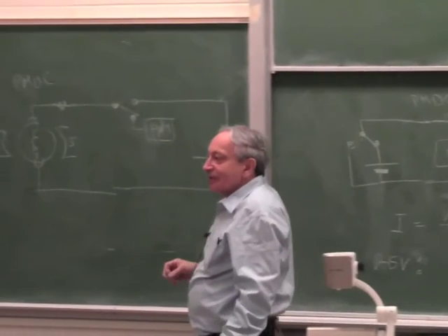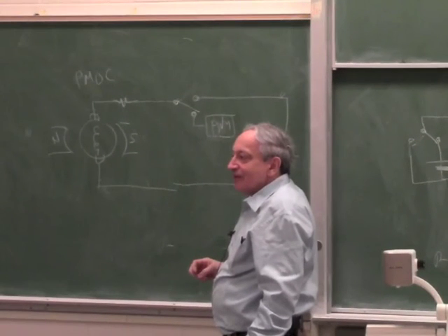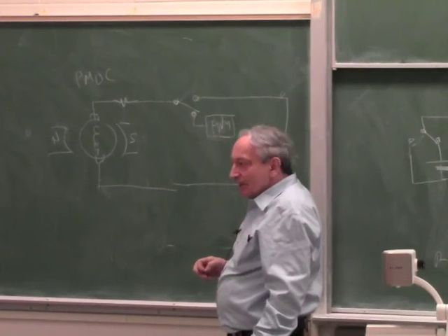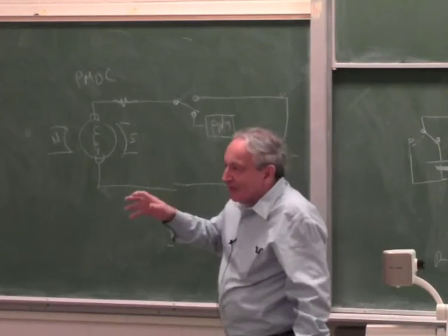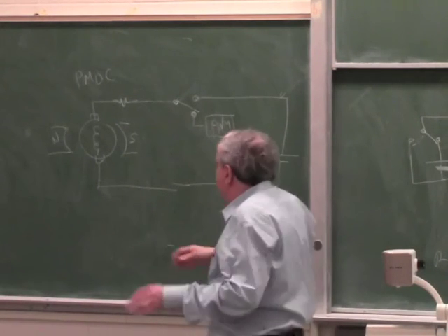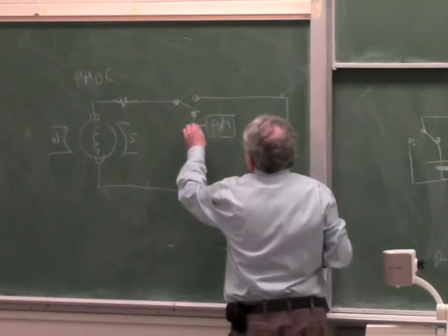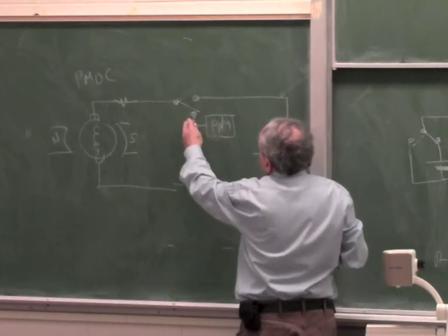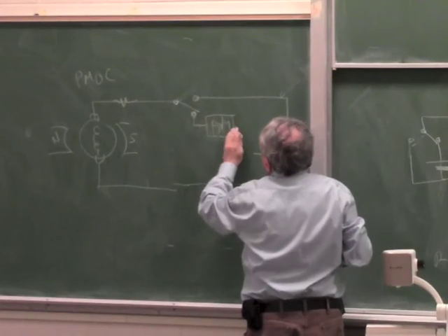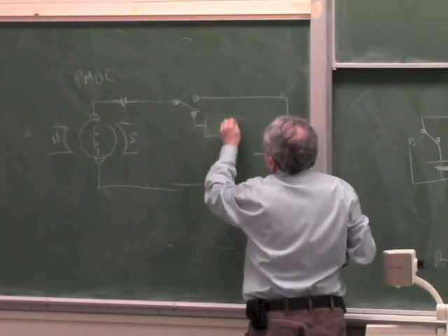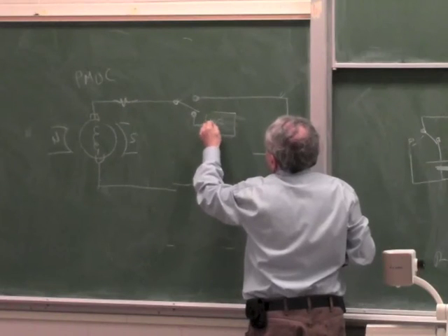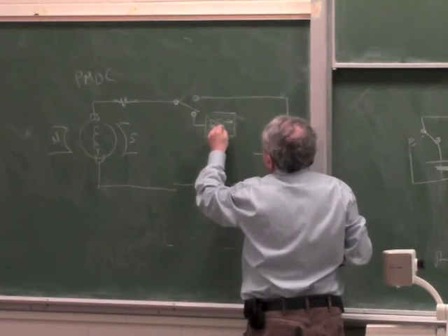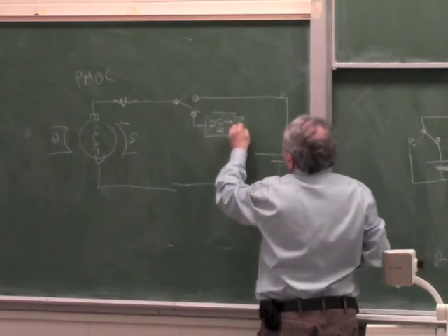Yes? Don't buck boost converters also, can you use them to increase or decrease the voltage? Yeah, but that's just a flavor. But in the more generic case, you change the voltage. In the most generic case, you have DC here. First, what you do, you make it into AC. You say DC to AC. Now you can run a transformer.